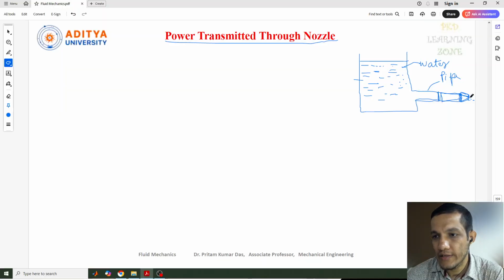This is to increase the flow velocity here, and this is the diameter of the pipe, D, and the total length of the pipe is L. This position is the inlet of the pipe, and this is the total fluid level. If we consider this the central line of the fluid flow in the pipe, then at this inlet position, the total head is present at the inlet condition.